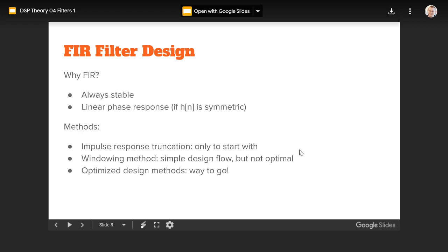Since usually it's also a so-called expensive filter, meaning it takes a lot of computing resources compared to the same amplitude response on IIR. For example, audio filtering with FIR would be a waste of computing bandwidth, because there the linear phase response is nothing.